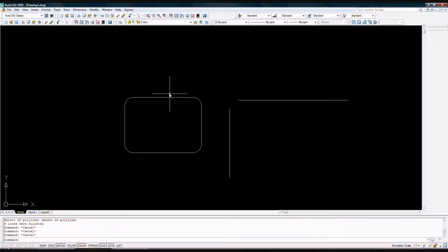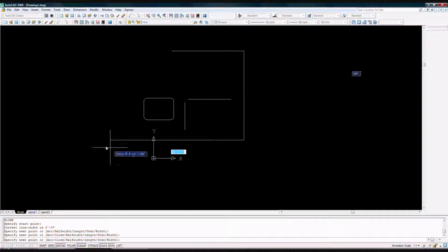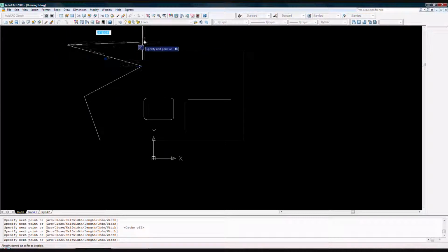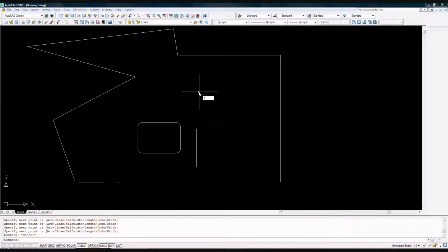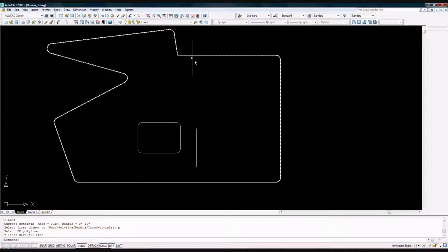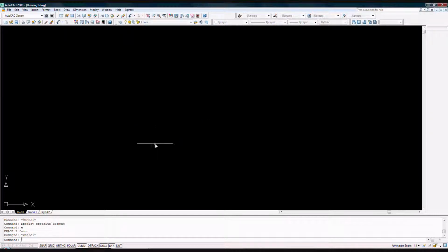It's useful when we have a multi-polyline. Say for example I have so many different directions of polylines, and I want to apply this, F enter and P enter. I have that radius set as 10, so I'm just going to apply it to all of the corners. It's going to turn out to be a 10 inches radius. That's how you do fillet.